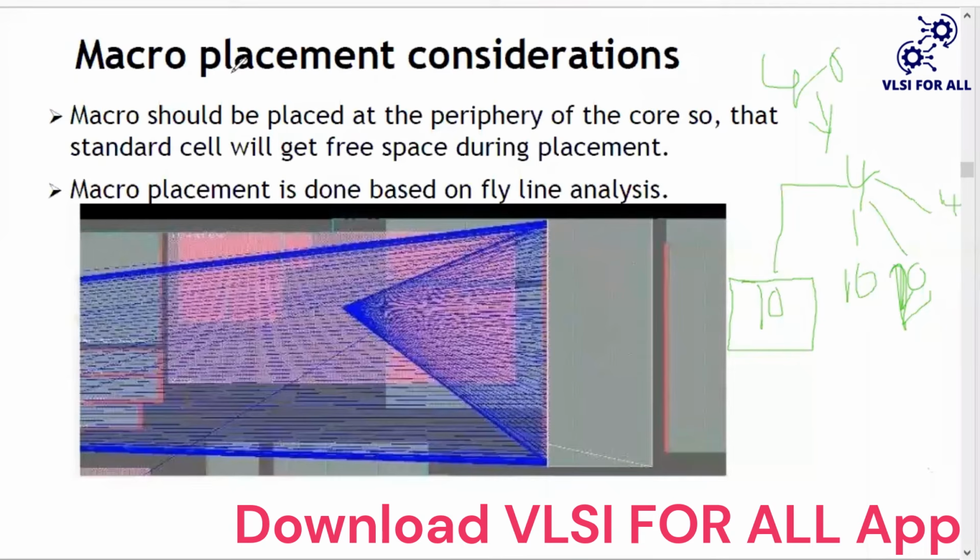If you change the macro placement or create some small issue, then total timing, PV, routing, or whatever specification, and at the last stage, the tape out stage, where the vendors check the specifications, the design will collapse. The total design depends on the macro placement only.